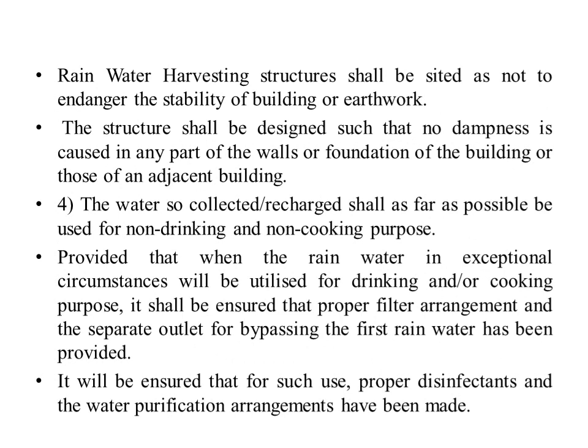Then the entrance landing. Entrance landing shall be provided adjacent to the ramp with minimum dimension of 1800 mm by 2000 mm. The entrance landing that adjoins the top end of the slope shall be provided with floor material to attract the attention of visually impaired persons, limited to colored floor material whose color and brightness is conspicuously different from that of surrounding floor material, or material that emits different sound to guide visually impaired persons, hereinafter referred to as guiding floor material in Annexure 1.